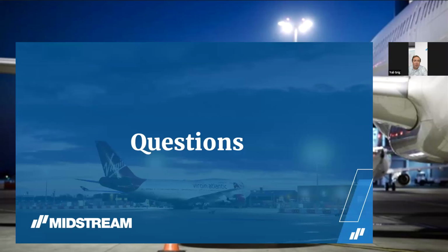What is the difference between ICAO and MOS 139? I'll just tackle that. I think MOS 139 is the Australian standards, and they're quite often exactly the same as the ICAO requirements. However, Paolo, do you remember the only difference in Australia was that for small airports, small aircraft, they had a different requirement, which was, I think, a 5 lux average and a different uniformity, or maybe the same uniformity. But Australian, do you recall from memory?